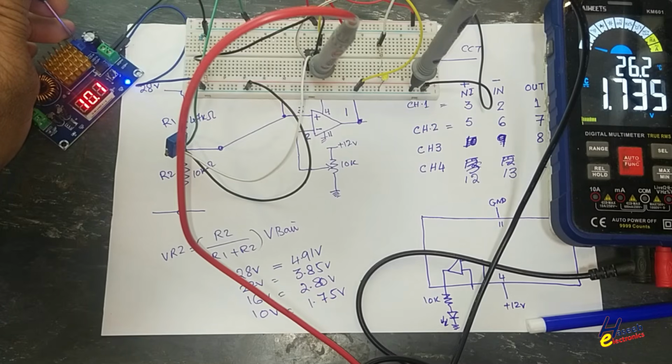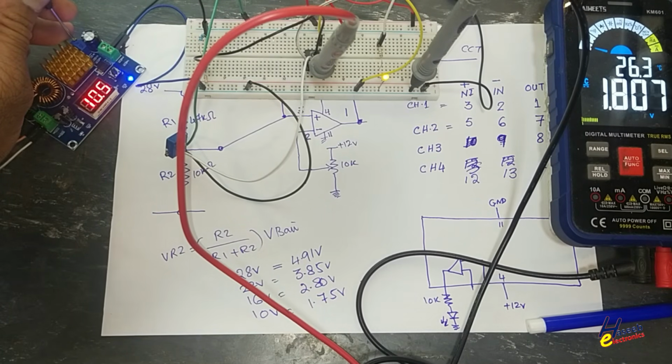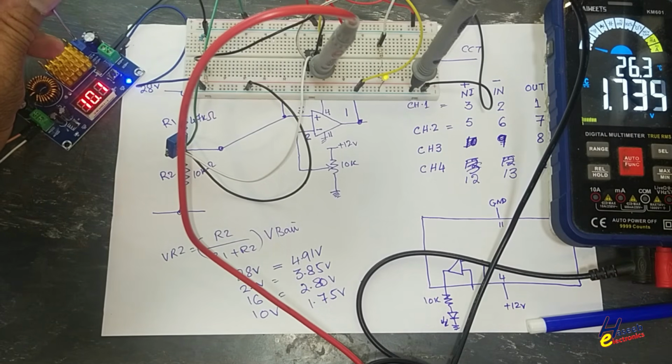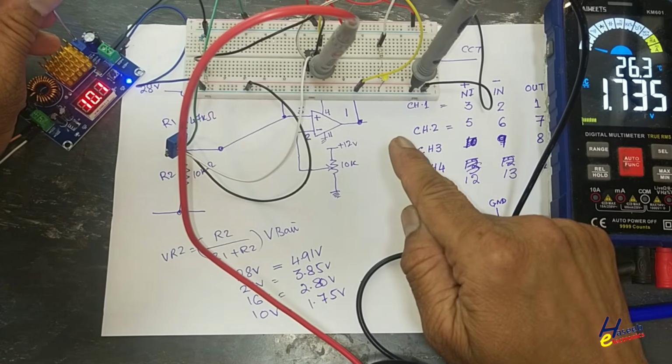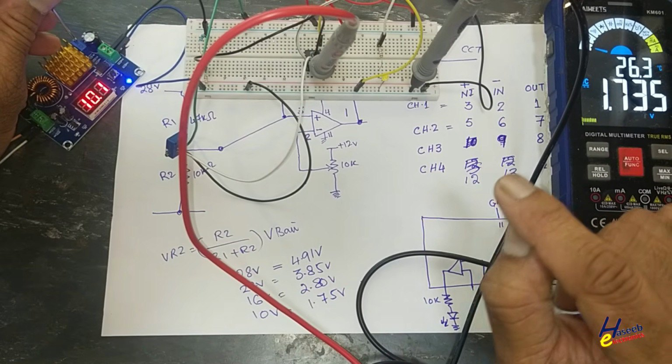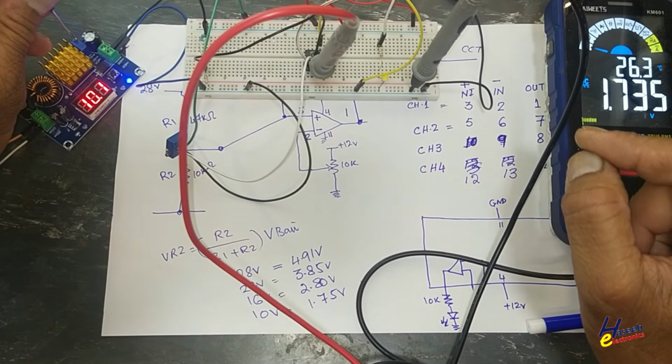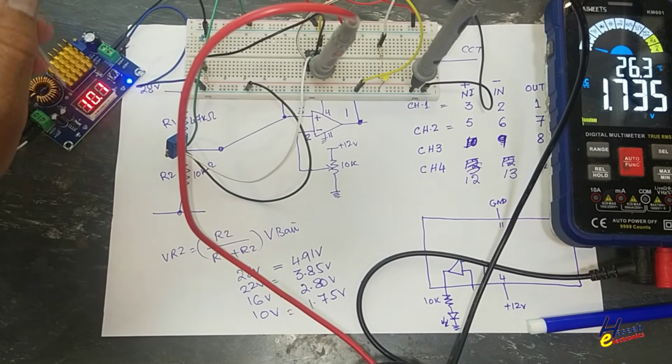To overcome this issue, intermittent condition, we need a positive feedback. If we don't use positive feedback resistor at that specific level, that is offset value, sometime it will turn on, sometime it will turn off.